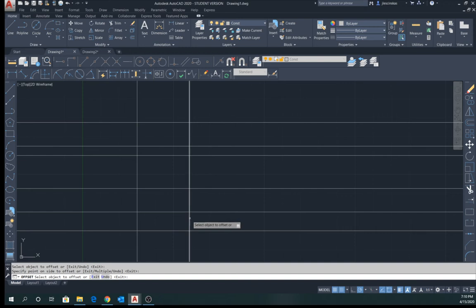From this line then, we have a line coming back in this direction that's 1.625. So put that in, offset 1.625, enter, click, put the line in, and another line also coming back from here of 0.875, click, move back,